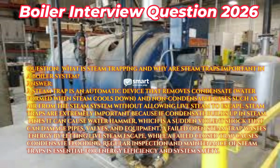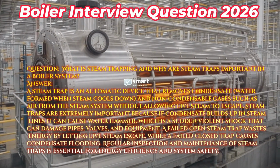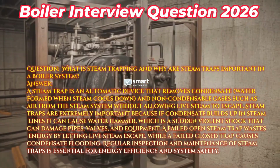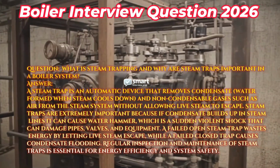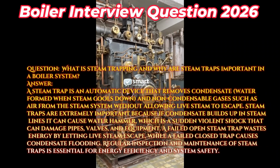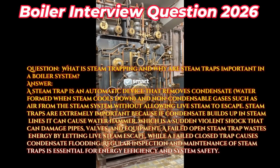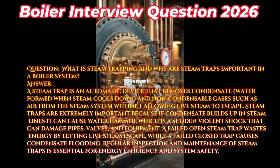Steam traps are extremely important because if condensate builds up in steam lines, it can cause water hammer, which is a sudden violent shock that can damage pipes, valves, and equipment. A failed open steam trap wastes energy by letting live steam escape, while a failed closed trap causes condensate flooding. Regular inspection and maintenance of steam traps is essential for energy efficiency and system safety.